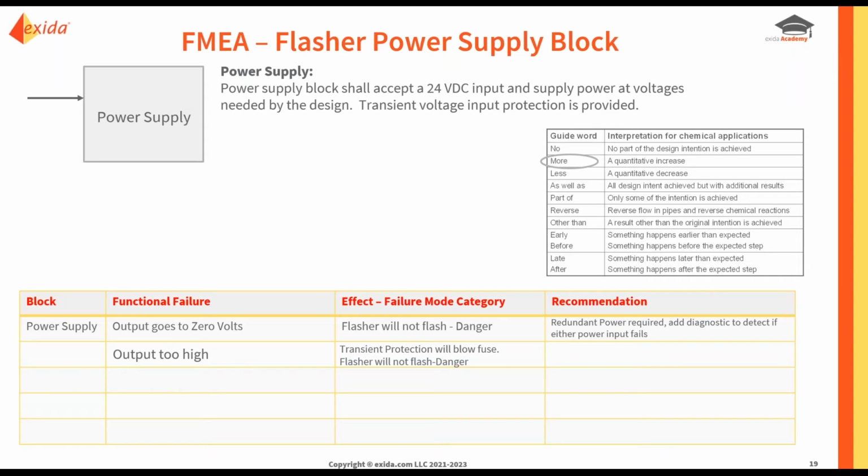are we sure the transient suppression device can handle enough current to blow the fuse? What if the transient protection blows out open circuit and the fuse is still intact? That would not work at all. That would wipe out all kinds of electronics. I think we better make sure we've got a very good test for that.